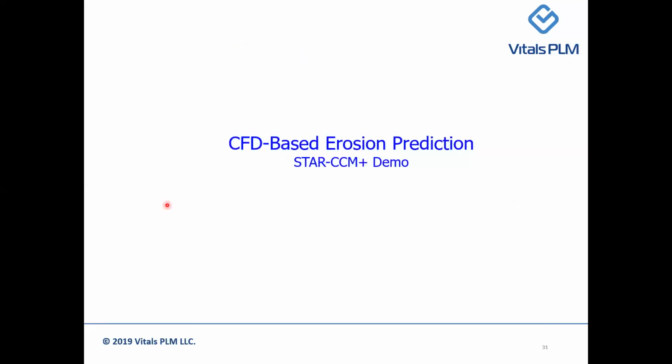In the continuation, I'm going to show a short demo on prediction of erosion using STAR-CCM+ software. The erosion can be efficiently modeled using a Lagrangian multiphase model combined with an erosion model in STAR-CCM+. So in this demo, we are using a standard Lagrangian multiphase model. For a high level of solid loading, we can consider using discrete element method, which is also a Lagrangian method, or granular flow model, which is an Eulerian approach.